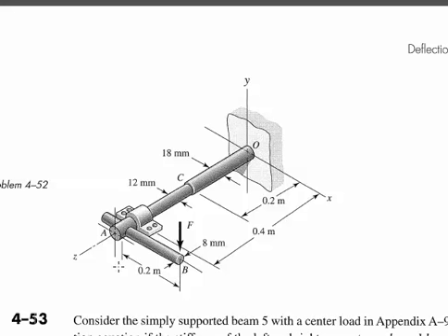And do note that the torque applied to these bars is a constant. It would be the force times this 0.2 meter distance. So the torque in here is a constant, the torque in there is a constant. That sure makes the integration really easy. But our bending moment when we choose our coordinate system will not be a constant. We'll probably measure our moments from the free end of this beam and move toward the left and look toward the right to write our moment equations. That's probably the way it's going to go. So let's look at adding all of these 3 terms up and coming up with a proper deflection for this thing.